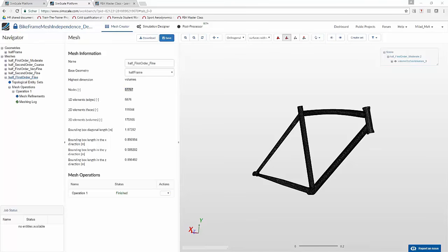Ode wants to know what is a good starting number of cells for any model. Ode, first of all, it's very hard to answer this question because it really depends on the problem. If you have a simple elastic bar, you may just need several hundred elements, while if you're simulating, let's say, a complex assembly, for example a crankshaft with springs and everything, you will need several hundred thousand. In general, this is very much related to experience, but I would start with a mesh which is as coarse as you think it can be, and then improve it step by step.